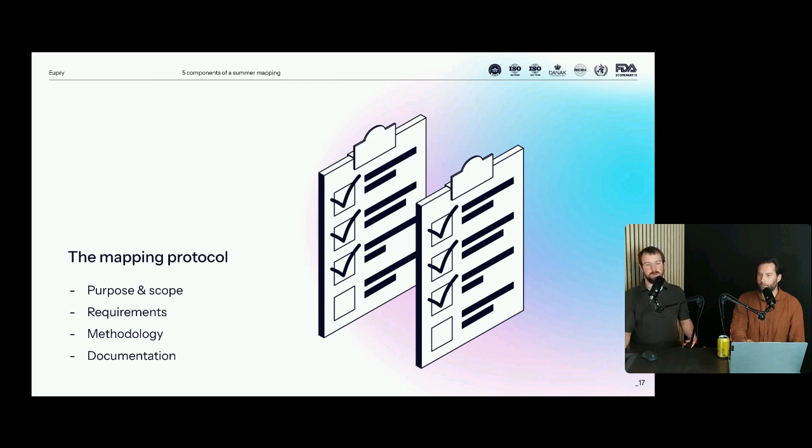So, first of all, the sampling frequency is something that should be part of your mapping protocol. You should define how often you expect to gather data. Unless we're talking about very high-speed processes, like autoclaving, it really doesn't matter that much.